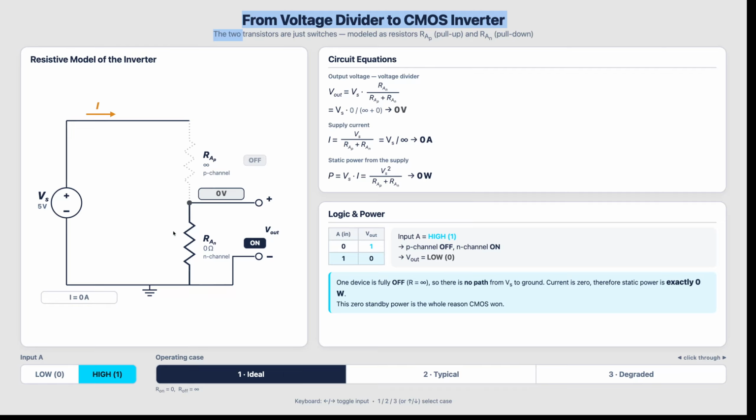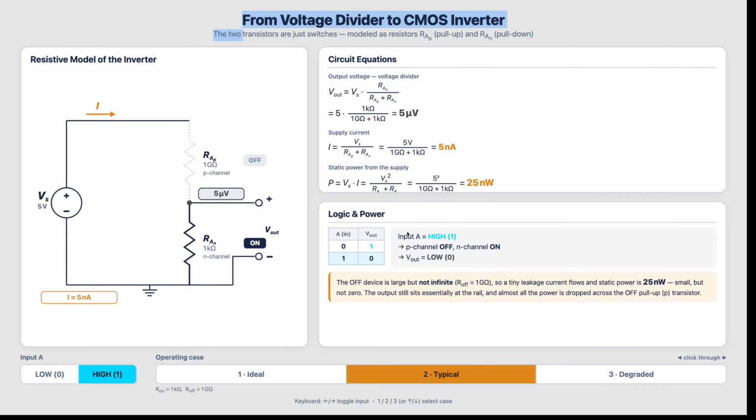The next thing I wanted to talk about is that in real life, these are transistor devices and they're not perfect. They don't have 0 resistance for short circuits. They don't have infinite resistance for open circuits. So again, we're actually removing a level of abstraction, where we can model what would happen if you had a typical load.